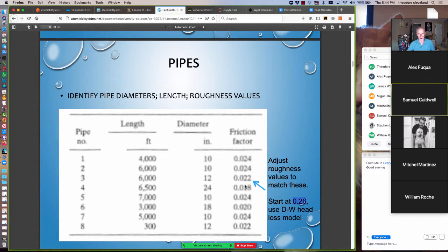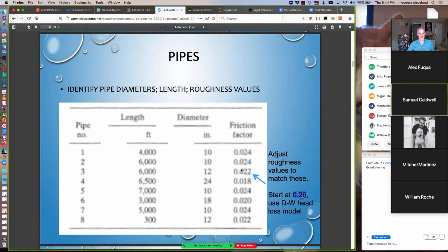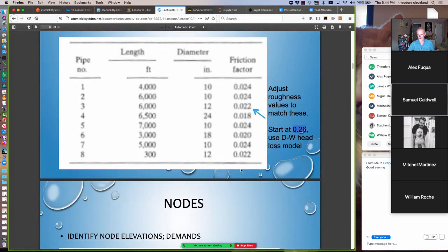They're not wrong. It's just the EPANET curve that estimates friction factors gets horizontally asymptotic quicker than you or I would looking at a Moody chart. I would argue that it has very little impact on the ultimate hydraulics, and so it's not truly a problem. But you do need to be aware of it if you're trying to match against older solutions. Older meaning 20 plus years or more.